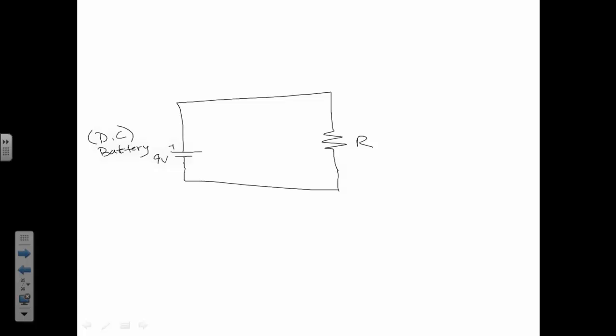If you try to drive a huge amount of current through it, you'll actually physically feel your wire heating up. If you feel your wire heating up, that means you're overloading that wire, and you're losing a lot of your energy as power loss in that wire, where you want it to go to your device at the end. But for typical conductors, we treat conductors as zero resistance, which means we have zero voltage drop. For typical purposes they're designed for, the resistance of the wire compared to the devices that you're actually driving is negligible.